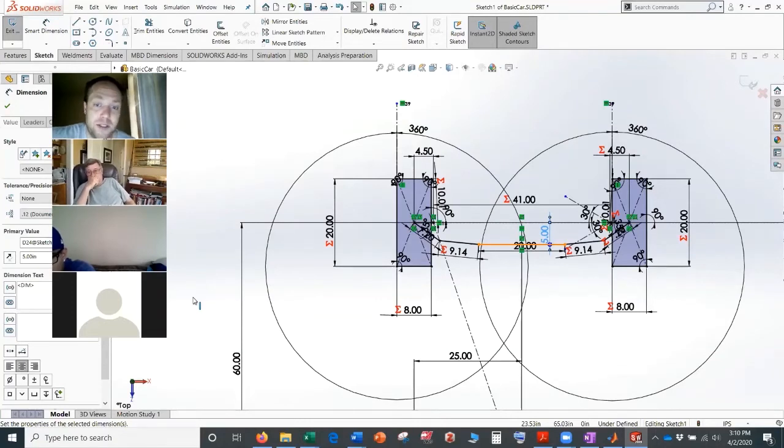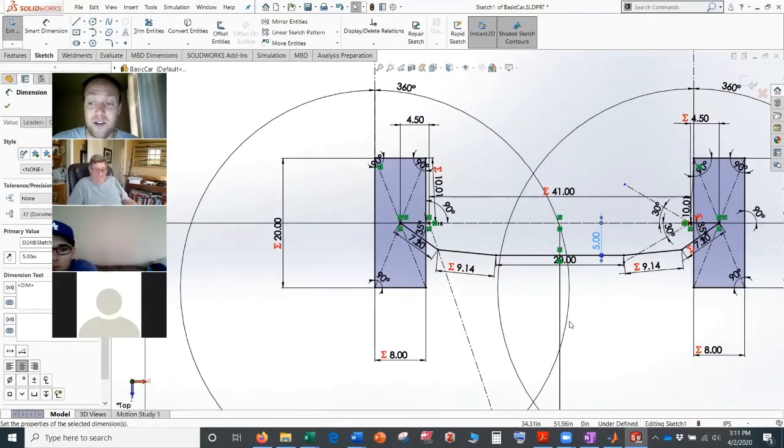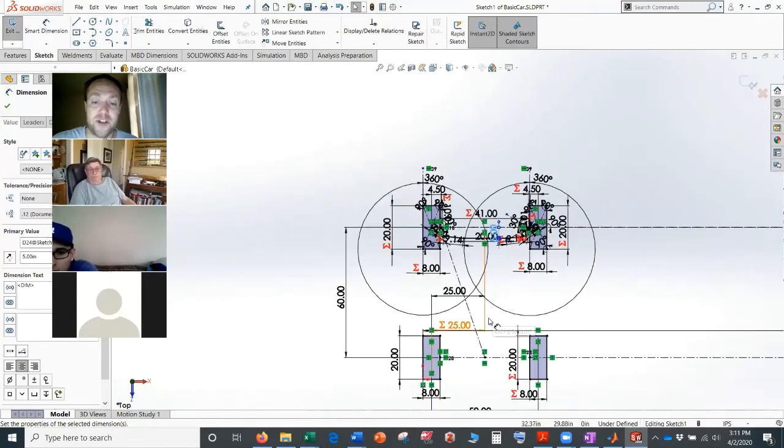Yeah, but the hard part then is you need to connect to your steering arm up in this area, right? To get Ackermann, if you do front steering, you've got to connect inside the wheel. So the inside-the-wheel packaging becomes more difficult for front steering, but you don't go over center as much. Imagine this rack is usually up here and it goes over here and over here, so they're almost pointing away from each other. Where here, they're almost already pointing along each other. So designing the steering is super over constrained basically.